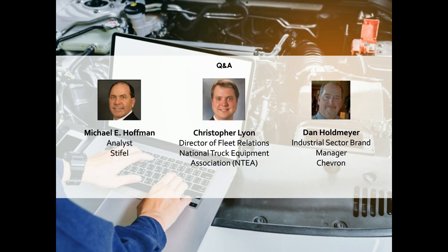You can utilize a CK4 oil, 10W30 or 15W40, in place of the FA4 oils. So you do not need to carry multiple oils for your engines. As long as your fleet has a good mixture of more modern engines that will handle the 10W30, or you can still go to the 15W40. But getting back to what Michael said, you want to look at your fuel economy. Where's the trade-off there?